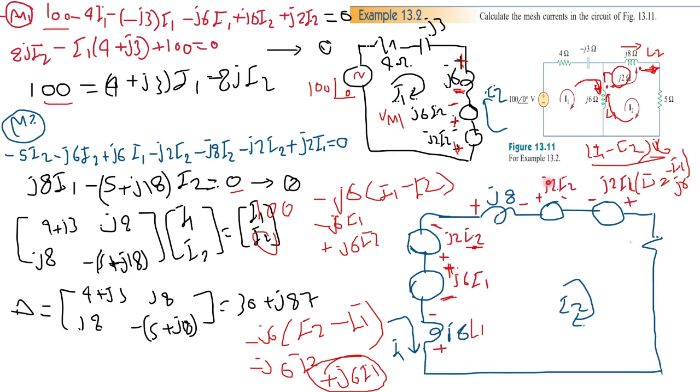Now for the mutual inductance, we have to check the currents. We have two currents, so we have to consider each current separately. I have I2 leaving L1 at the dot and leaving L2 at the dot, so this is an aiding connection case, meaning that the mutually induced voltage around L1 because of I2 passing through L2 would have the same polarity as the self-induced voltage. Here is a voltage drop, positive here and negative here.